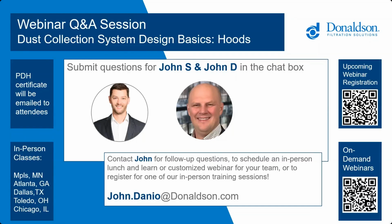In the duct webinar, we'll have a little more discussion about elbows and entries and things. We highly recommend using either US Duct or Nordfab duct, because it's designed for dust collection specifically. The elbows and the fittings are designed to pneumatically convey dust through the duct, as opposed to spiral duct, which can be very effective as well, but you have to be careful with your elbows and fittings because you may end up with very inefficient ones.